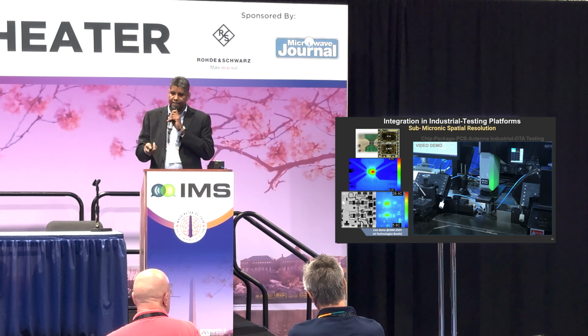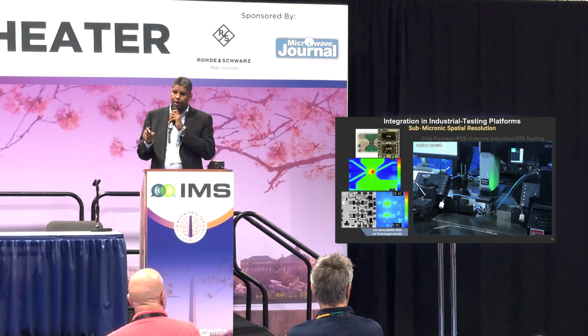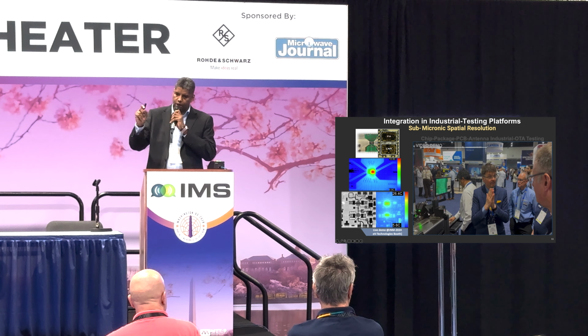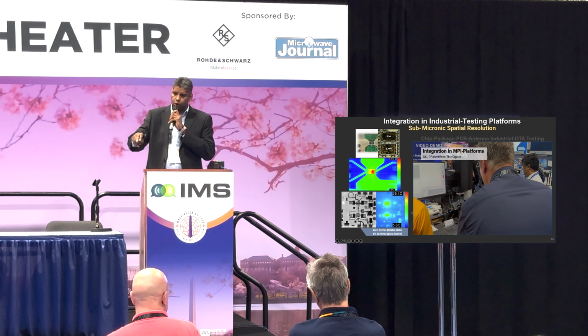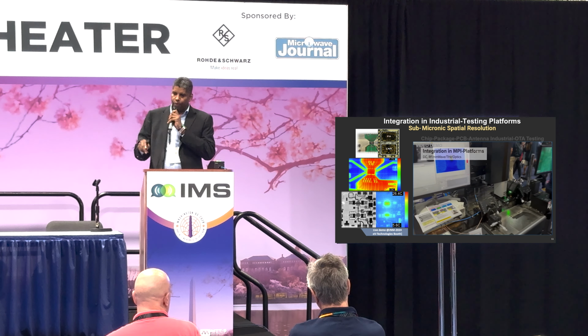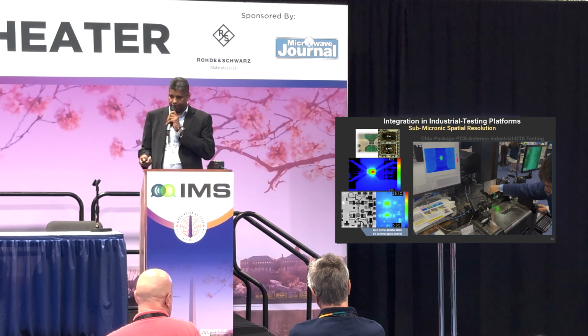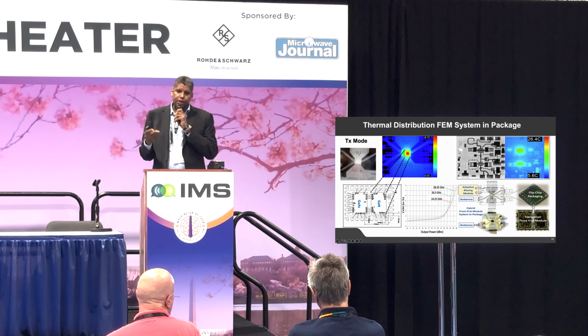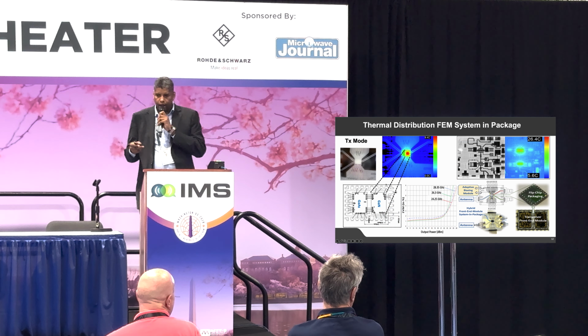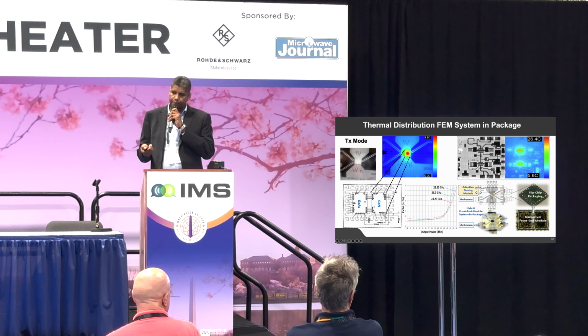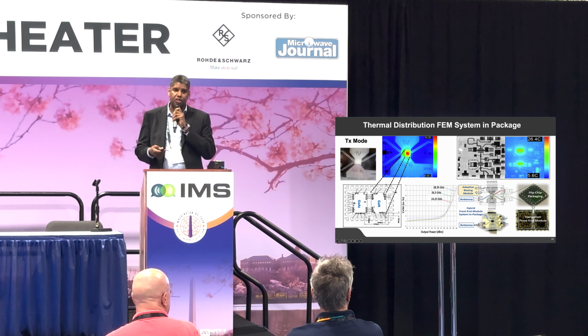On the left side you see an application where we have been using system in package technology with a power amplifier and a low noise amplifier, and you can see in real time, in time domain, how the power and the dissipation flow through the circuits. Much higher resolution is seen on the bottom side, where you can almost see the power within the transistor itself. We have pushed the analysis farther in checking how this type of device can be combined with antennas, and how it can be combined and checked against the packaging technology.